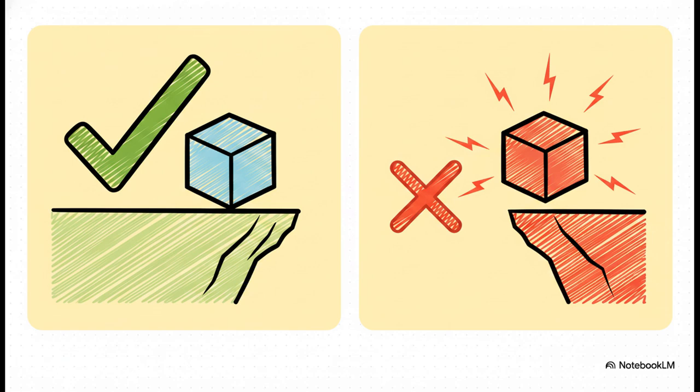A stable system will show a positive gain margin in decibels and a positive phase margin in degrees. A positive margin on the plot is literally your safety buffer. It tells you how much wiggle room you have before things fail. Conversely, if those margins are negative, your system is unstable and you've got to redesign it.